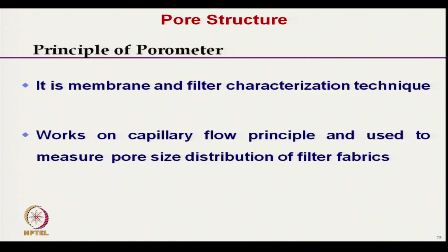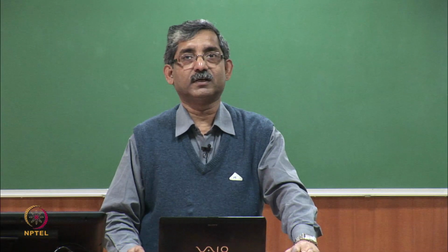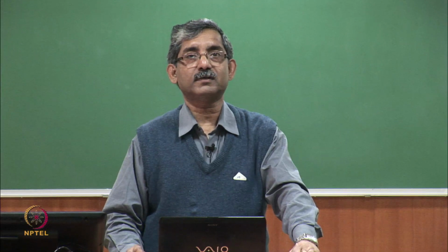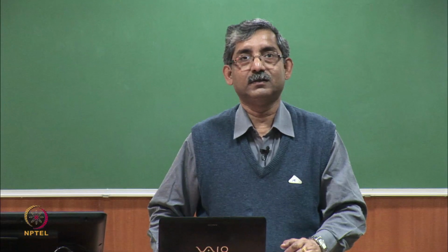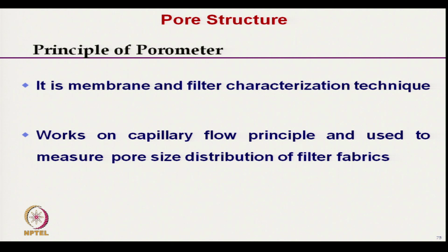Let us discuss the measurement technique of pore structure. The pore structures are measured using a porometer. There are different types of porometers. These are used to measure the pore structure of membrane or filter fabrics, and these are important for filtration characteristics.